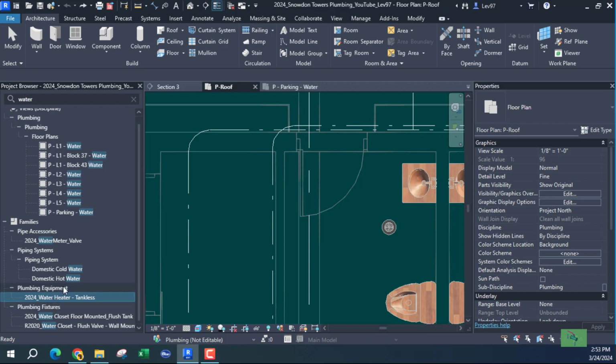I don't know if you guys are aware, there are certain types of families that come in with, let's say, a type catalog, where you have an option from a 1-inch type of family to a 2-inch, and there's a list. So I think the reason that you can't drag in your family is because there are going to be several options. So just keep that in mind. When you search for information, you can double click on a view, but you can't drag your family over.